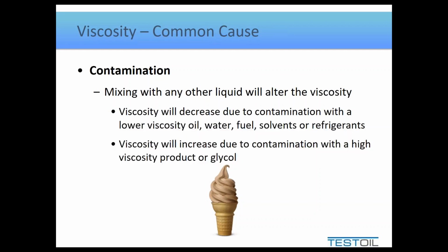So most of the time that we have water content, we don't see much of a change in viscosity, and when we do, it typically tends to be a decrease when we get to higher levels of water. To be fair, if you got extraordinarily high levels of water, you would cause an emulsion and you would see a viscosity increase, but at that point, that'd be your least concern, and the question would be, where's all the water coming from? Getting back to glycol, though, glycol at even low concentrations will form an emulsion much more readily,